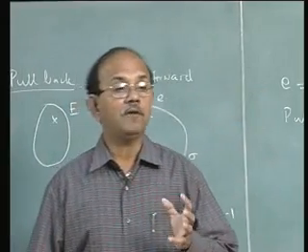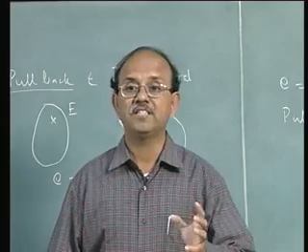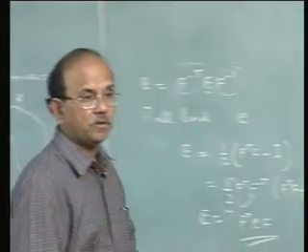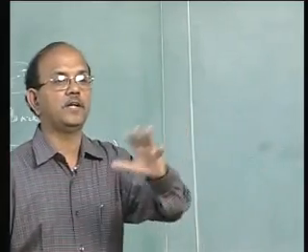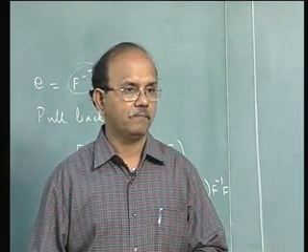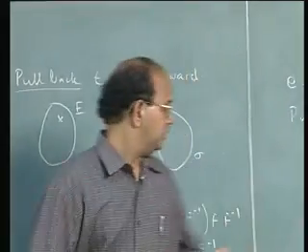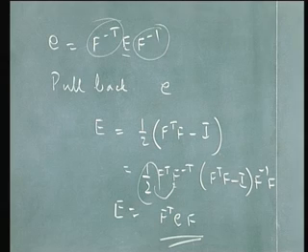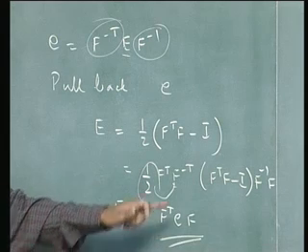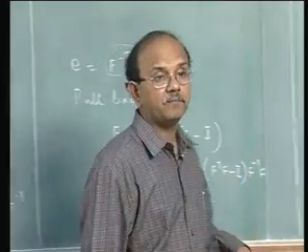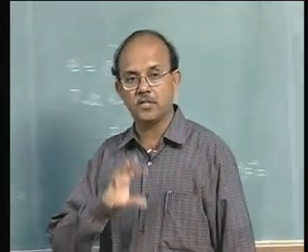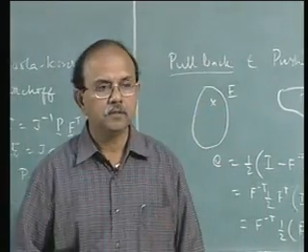When you have these two terms, the stress term and the strain term, one is the conjugate of the other. Ultimately, when I calculate the stress power, whether I do that in the current coordinates or in the reference coordinates, I should get the same stress power. If I have the same transformations for the stress, then when I multiply that by sigma, in other words delta epsilon transpose sigma, F will enter into my stress power term, and I will not get the same value on two reference configurations. So stress is what I called the conjugate of the strain.